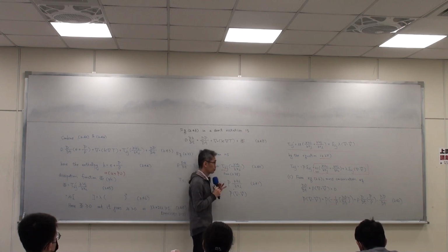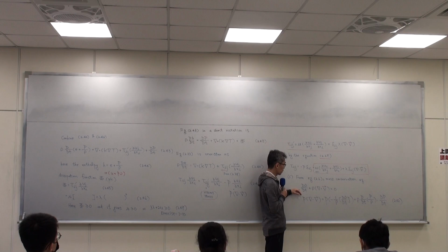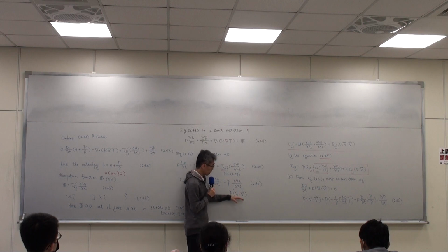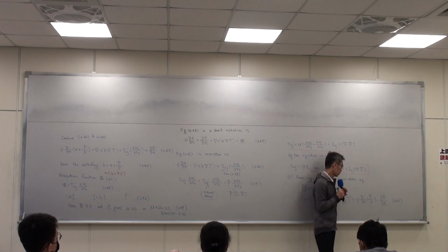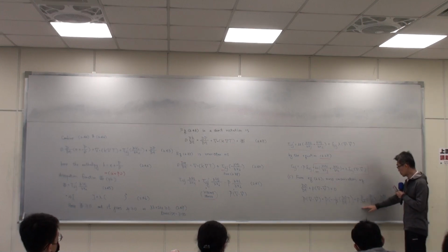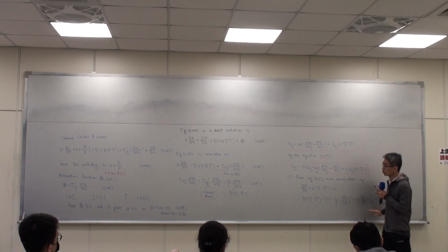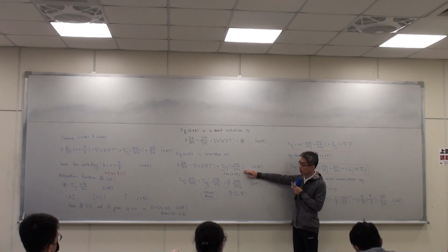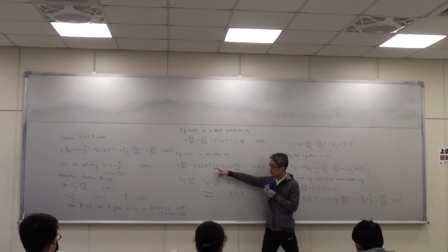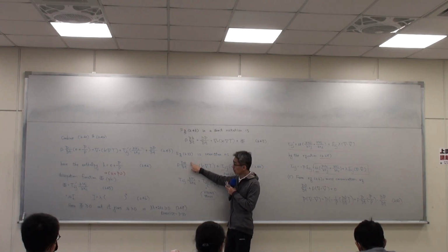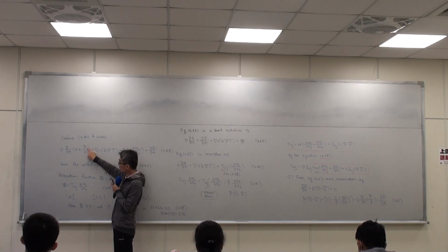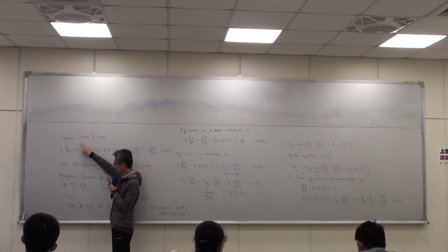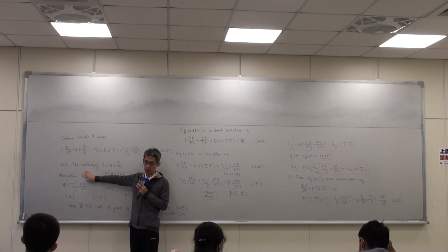So for this pressure, we can use the mass conservation equation to rewrite this term on the right-hand side. If we substitute this part into this energy equation with the internal energy, then we can sum the internal energy, the pressure and the density. This will become a new physical parameter, enthalpy.